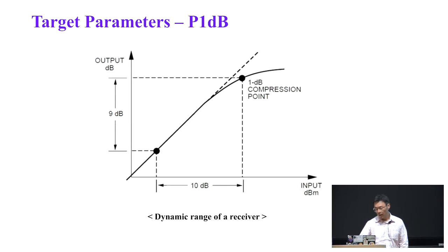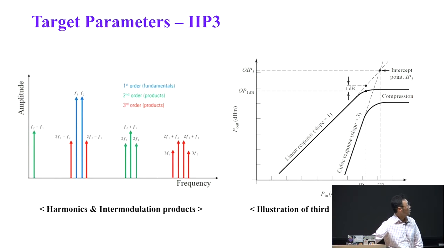Another thing to consider is that the Skywater PDK uses a really high VDD, which is 1.8 volts. Compared to recent technology, which uses maybe less than 1 volt as a power supply, it doesn't make sense to aim the target at low power consumption.